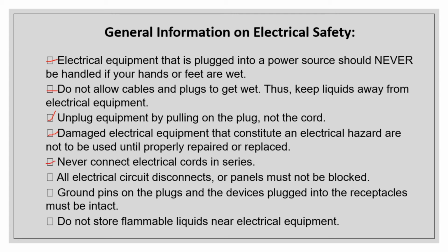Never connect electrical cords in series. All electrical circuits, disconnects, or panels must not be blocked. Ground pins on the plugs and devices plugged into the receptacles must be intact. Do not store flammable liquids near electrical equipment.